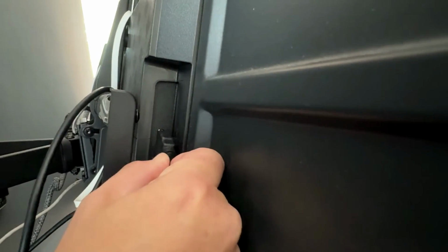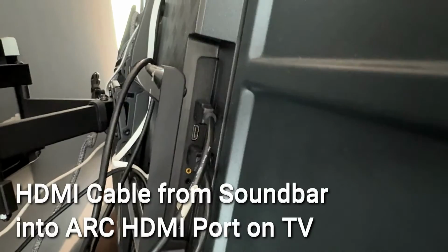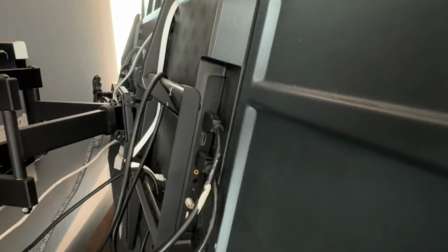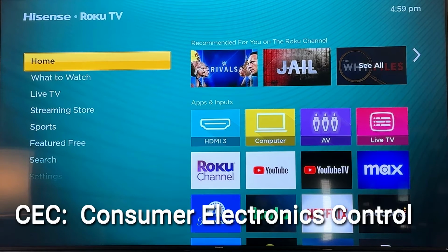Okay, so now the HDMI cable is plugged into the ARC HDMI port. Now that the ARC HDMI soundbar is connected to the ARC HDMI port on the back of the TV, we can now go into the television settings and get this connected. And all of these TVs that support ARC are going to have a feature called CEC. So what we're going to do, in this case on my Roku TV, we're going to go to Settings.